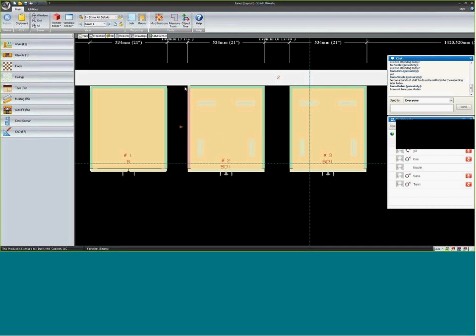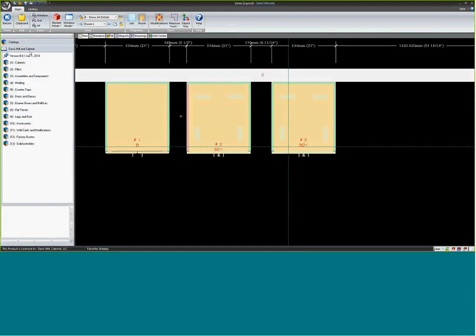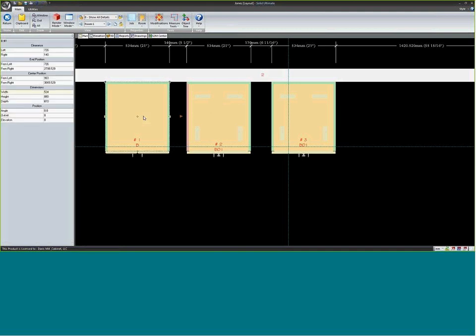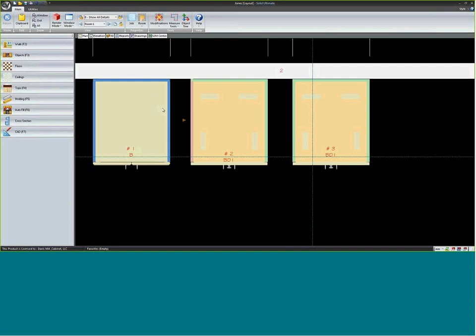on the other side. If I have a finished veneer interior cabinet, let me find a wild card, and we'll go to finish and finished interior. I'm going to drag that wild card out on this cabinet. Now I click that cabinet and double hit enter to refresh the cabinet like we talked about yesterday. Now notice a blue color. Blue denotes two-sided veneer, so you know now that this cabinet is all finished veneer.